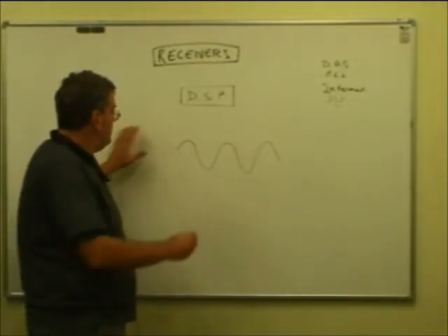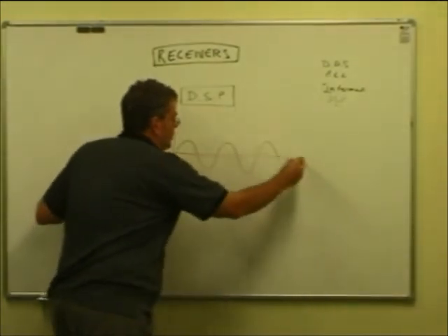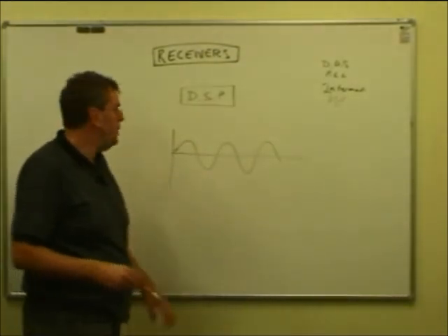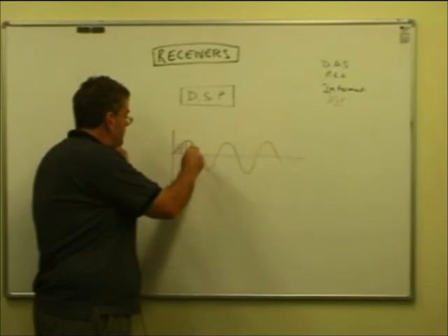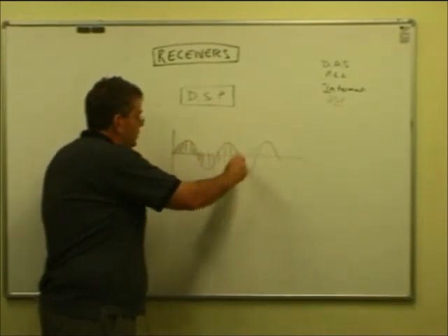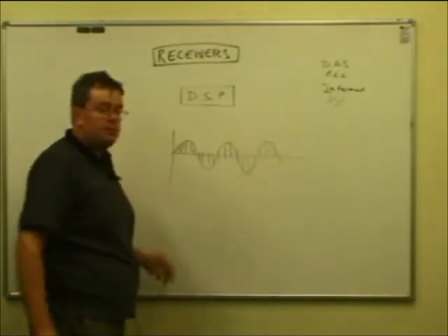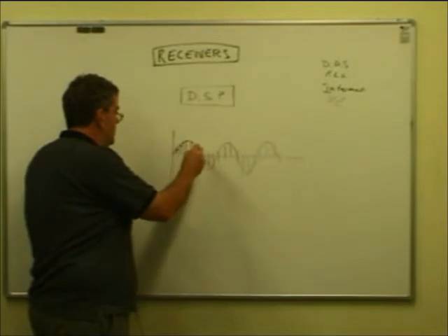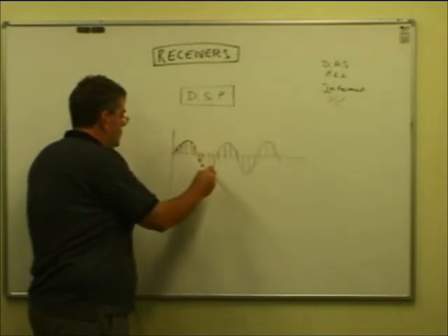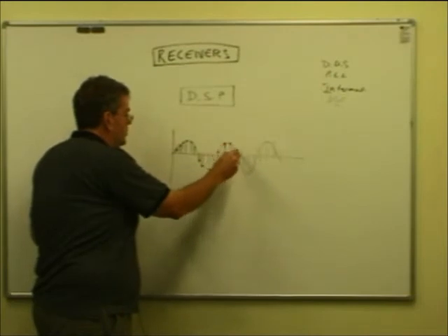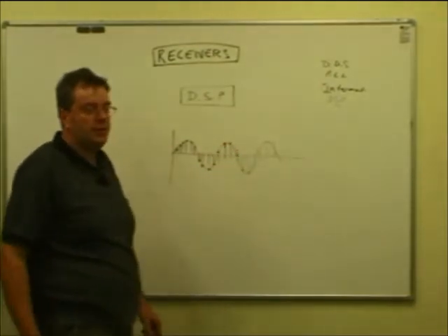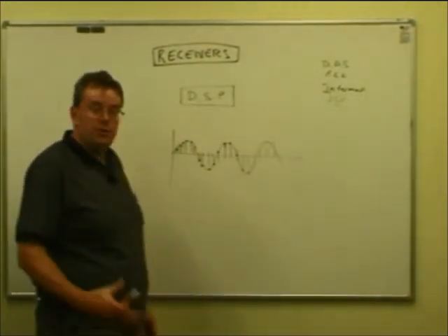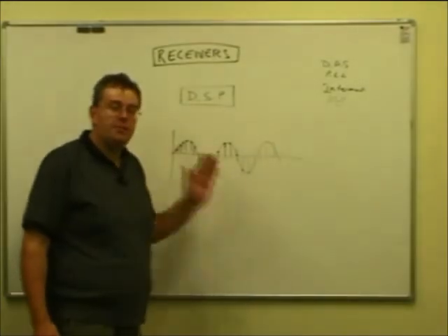But in a nutshell, what the radio is now doing is the same system used for encoding information onto a compact disc. At regular points, regular time intervals, the system takes a measurement of the amplitude, the voltage of the signal, and converts it to a digit. It digitizes it. It converts it to a digital number, generally done in binary, which is ones and noughts, which computers can handle. So it converts it to a fast stream of binary numbers.